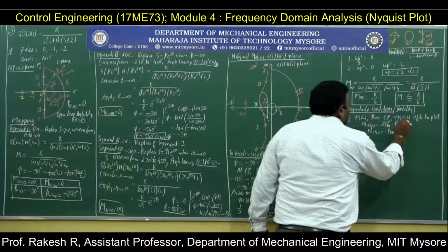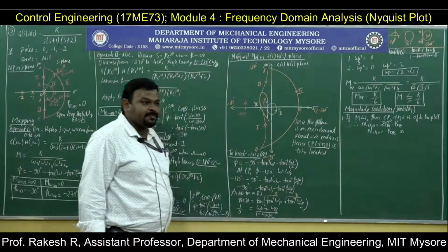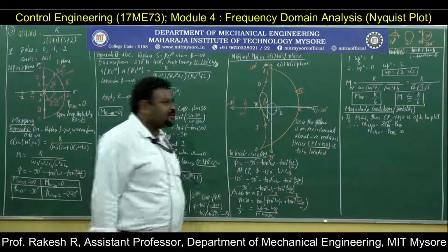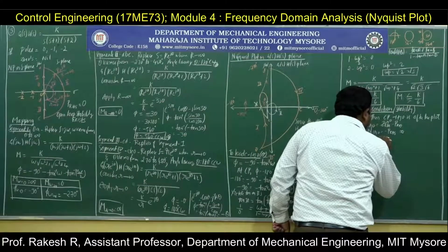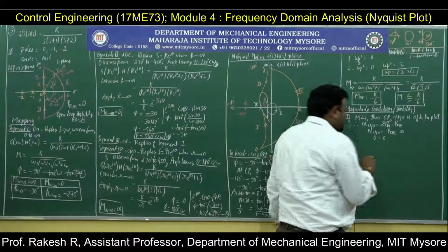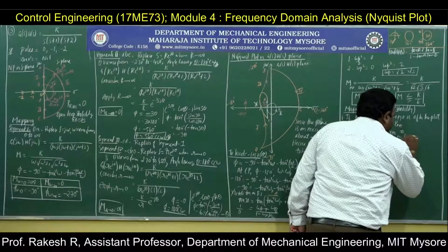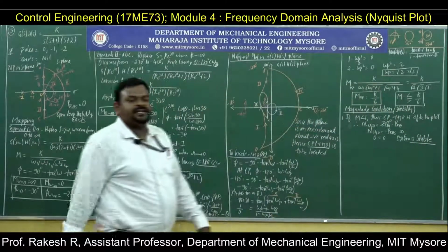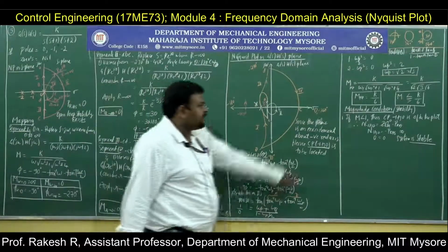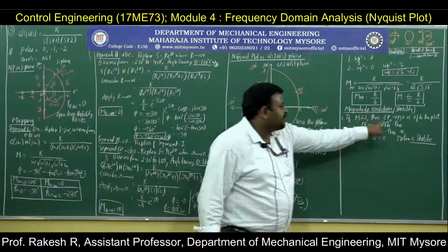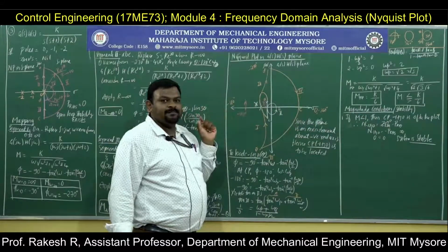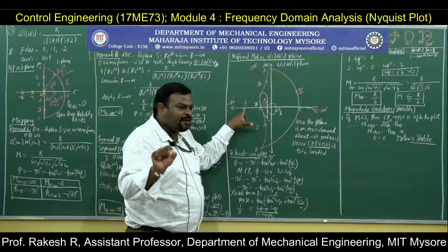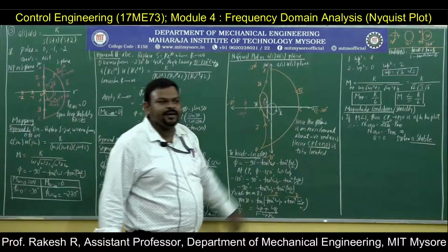So, what is N minus 1 plus j0 here at this point? There is no encirclement here. Is there any encirclement? No. So, 0 here. 0 will be equal to 0. Since LHS is equal to RHS, system is stable. In the first case, the system is stable when the magnitude is less than 1. Why? The critical point will be located after the plot. After the plot, there is no encirclement. At this point, is any polar plot crossing here? No. That's why it is 0 or nil.